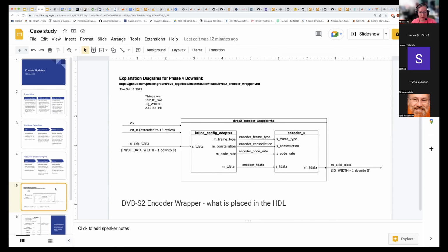Data width is 32 bits. It's expecting 32 bits in. And so that's the bus mismatch that we just fixed yet again. The default from the reference design is 128, and we forgot to change that. We thought maybe some of the more recent problems were because of that, but cleaning that up didn't fix it, or didn't fix it completely.